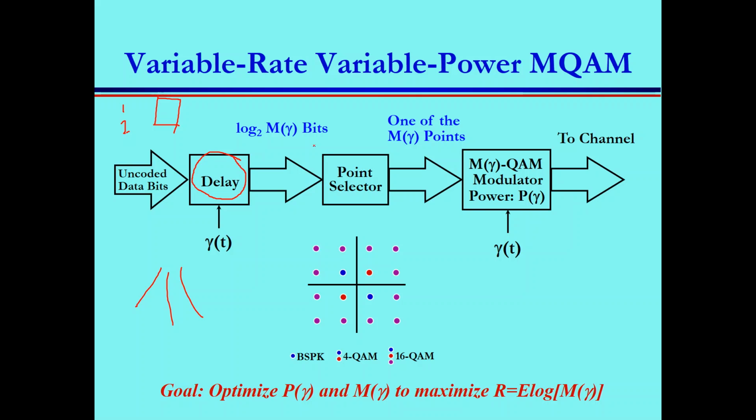And now you select your modulation after you decide based on the signal to noise ratio. We call it N, the modulation order, a function of what? The signal to noise ratio, which represents the channel quality. And then here you can also optimize your power as a function of the signal to noise ratio and send to the receiver over the channel. Clear? This BPSK, blue with red QPSK, all of them 16 QAM. Nice.